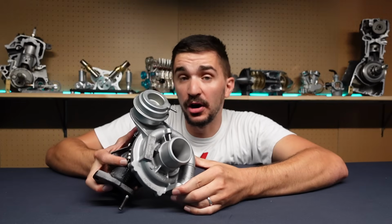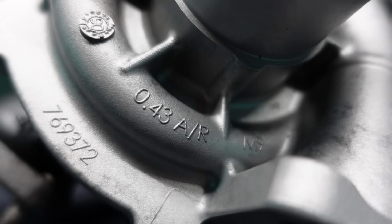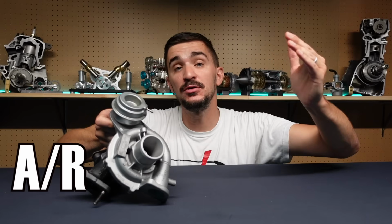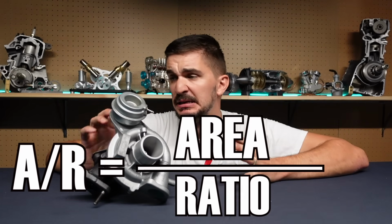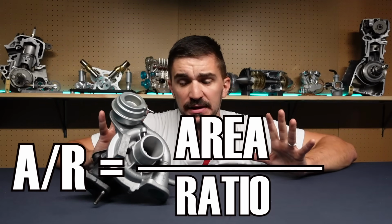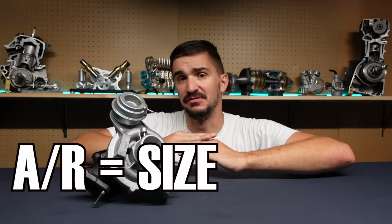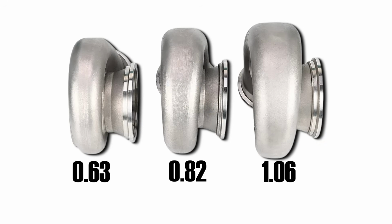The A over R number that you can find printed on the compressor or the turbine housing of a turbocharger simply stands for area over ratio. The simplest possible explanation for this is that it's the size of the compressor and the turbine housing. The larger this number, the larger the housings, essentially the bigger the turbo.